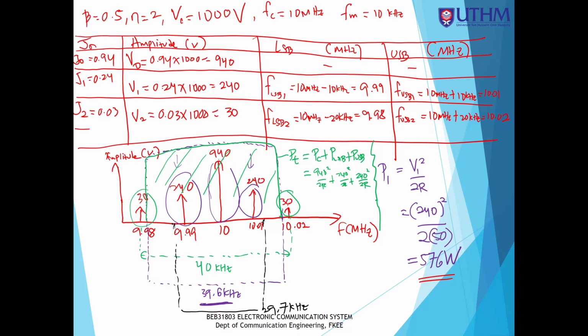So that is the thing about this 99%. In my opinion, this 99% wants to relate with the filtering process. The filter selects only 99% and removes the others. So within 99%, the total power would be up to the first sideband. The smallest power is at the first sideband, which is 576.